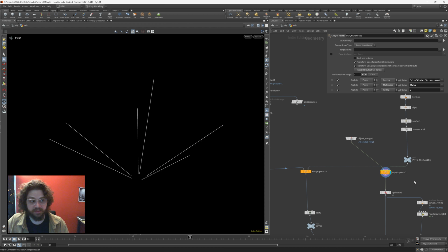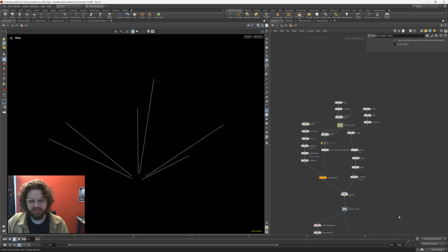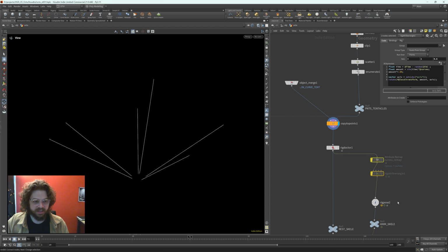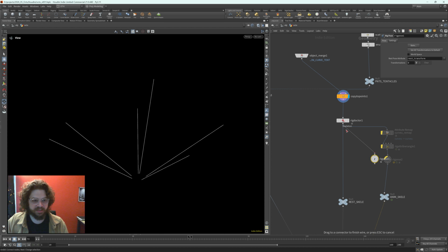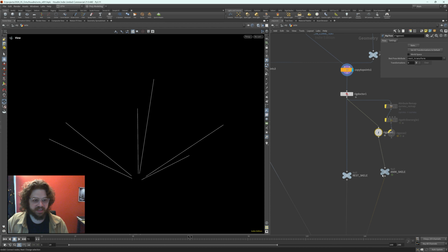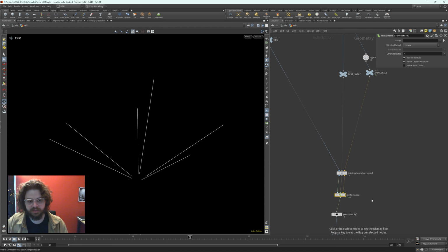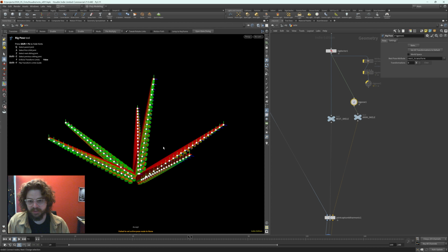They're all the exact same length because they all are created from the same original line here at the very start. So then we just need to animate. I'm going to disable these nodes and explain that in a second. I'm going to add a rig pose here to the rig doctor and plug it into the anim skeleton. And I'll put my view flag here right on the joint deform. And that will just take a second to initialize the skinning the first time you put your visibility flag there. And now I can go to the rig pose, press enter.